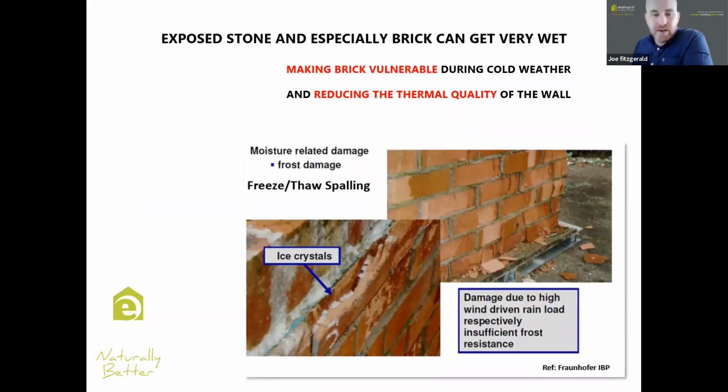So things like brick can get very wet. And if you've got bad pointing or missing pointing, the brick doesn't drain adequately. And then you get freeze thaw conditions causing things like spalling, or basically the face of a brick exploding. Now, when that happens, the inside behind the crust of that brick is much, much softer. So it tends to degrade really quickly at that point. Once you get a little bit of damage, you tend to get a lot of damage relatively quickly straight after.